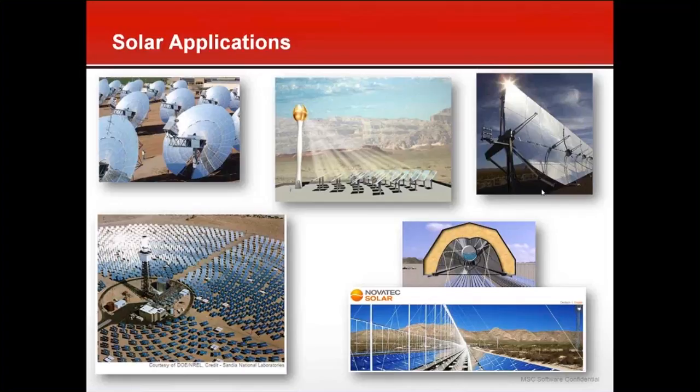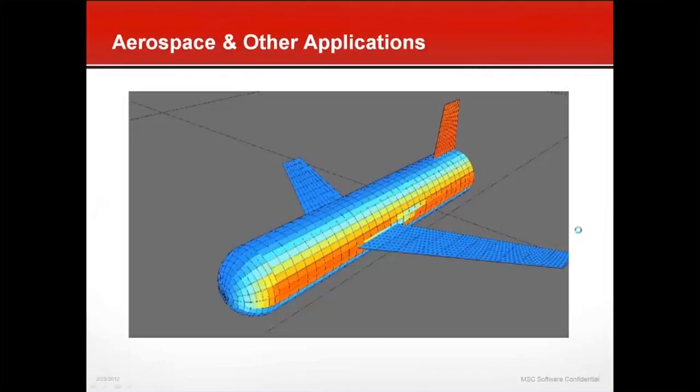You can describe any arbitrary kinematic motion and it will compute the dynamic view factors, the time-dependent view factors, time-dependent fluxes into all those surfaces, and specular bounces off mirrors into tubes of liquid flowing down like this parabolic trough, and this trough then can track the sun with 1 or more degrees of freedom. So we have all those features, and here's an example just to show you solar heating application on the Earth.